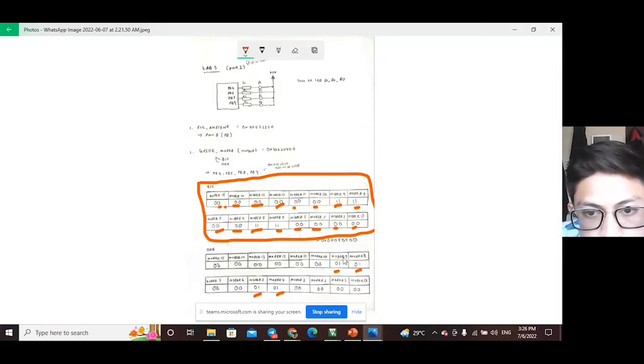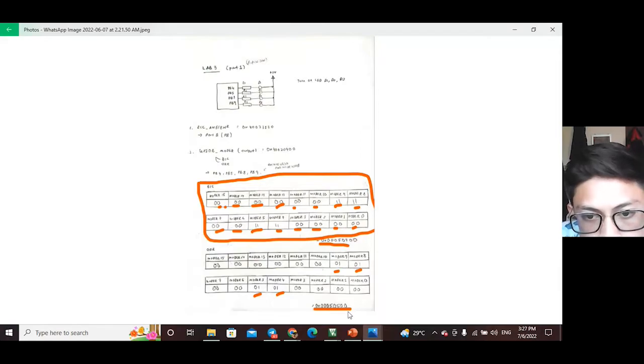So for the value of the BIC, we will get 0x000F0F00. This is the value that we will put in the coding for the LED. And this is the value for ORR, which is 0x00050500.